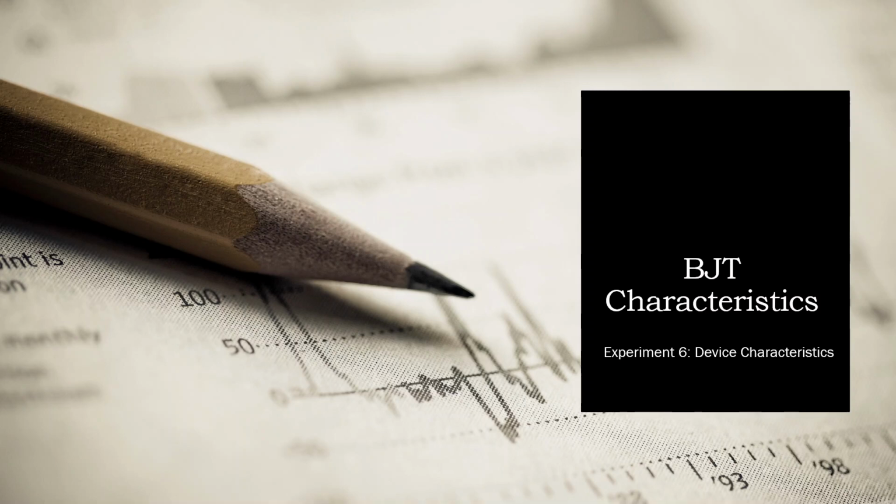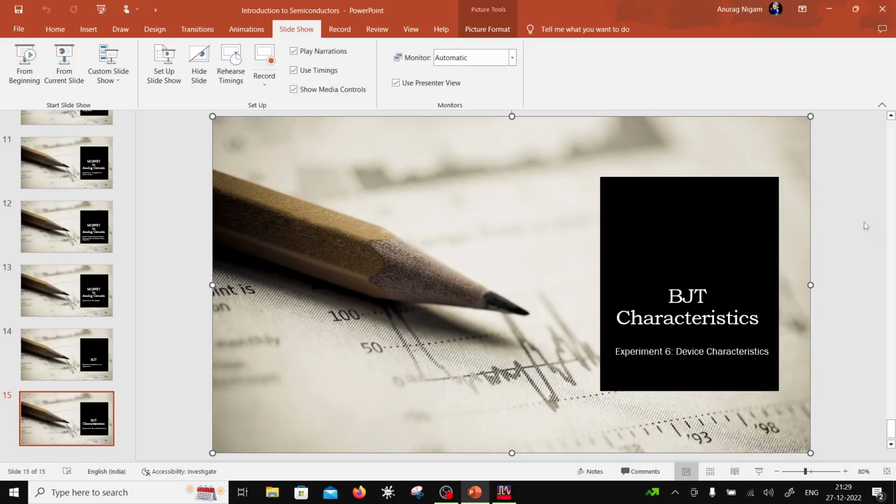In this experiment, we are going to talk about the bipolar junction transistor, and we are going to simulate its DC characteristics, see two forms of biasing. First is biasing using a voltage and biasing using a current. So we want to see the effect of these two on the output resistance and the breakdown voltages. And I'm going to explain two breakdown voltages associated with a bipolar junction transistor. So let's get started.